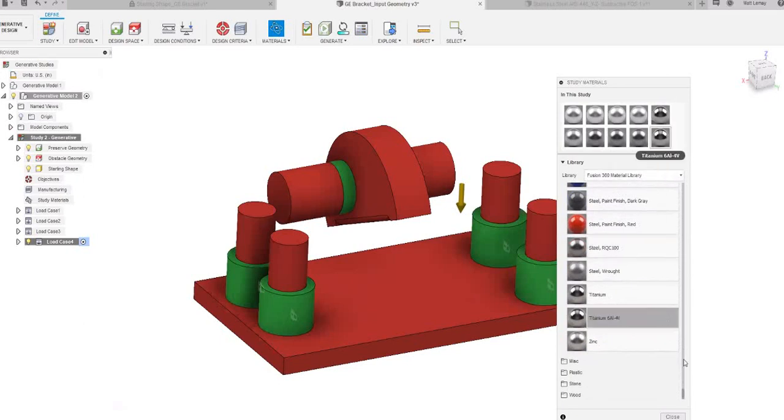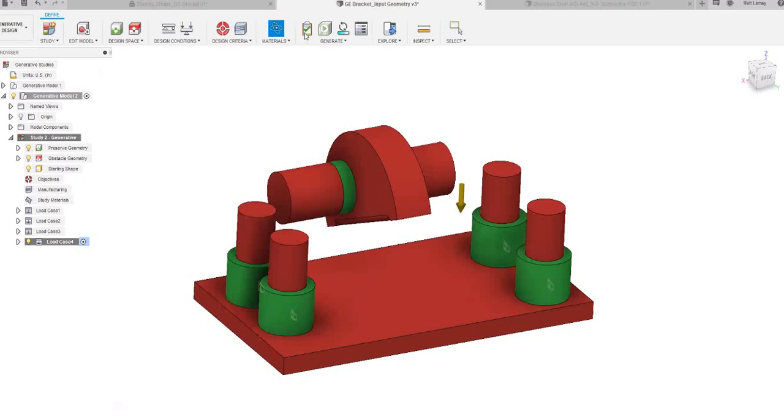So after we've added as many materials as we'd like to explore with, we see this green check mark here. That's a pre-check saying that everything has been set up correctly, and the setup has all the information required to run effectively. And even still, before generating, we can also run a local preview. And what this will do is it's taking your geometry, it's taking your loading conditions. You can see this toolbar at the bottom right. It's going to create a very quick local preview within about 15 to 20 seconds, just so you can ensure that everything's been set up correctly.